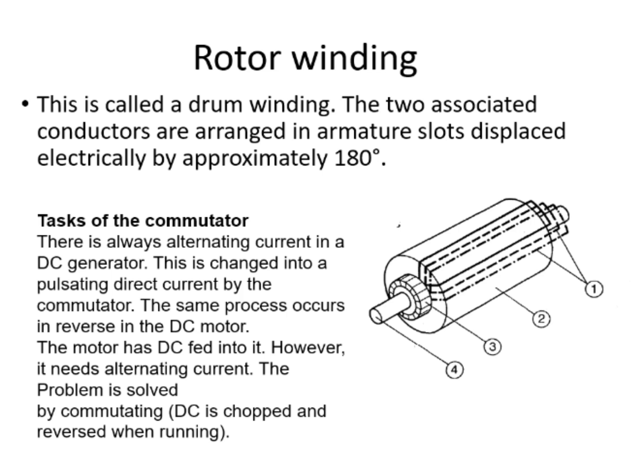It's like a full wave rectified signal of an AC waveform. In the case of motors, the same process happens the other way around, in the reverse direction, because for a motor to rotate we actually need alternating current, but we have to provide DC for DC motors. Then this DC is converted into alternating current using the commutator.